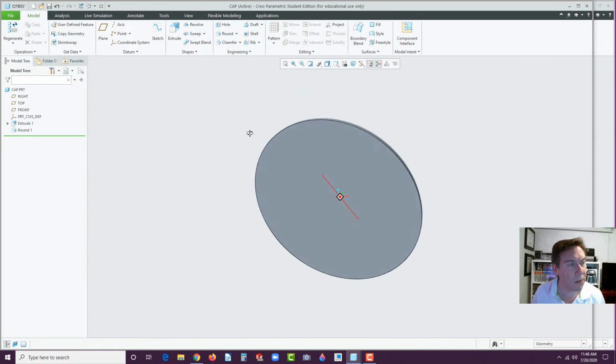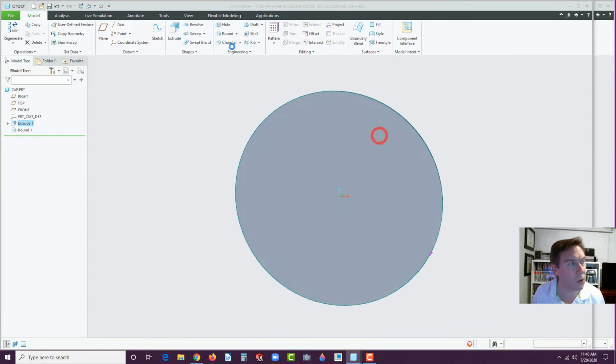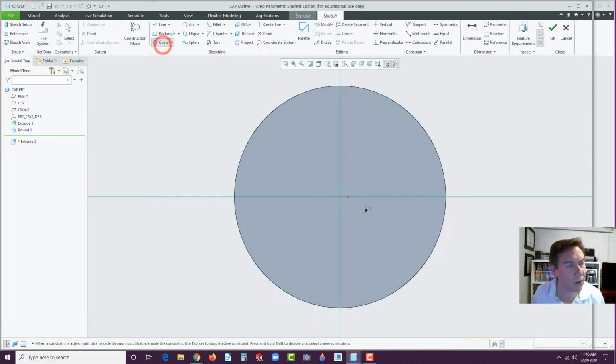Okay, now flip to the underside, select this face, go to extrude, go to the circle tool, and right at the center, drag out a circle and dimension this 1.8, so it steps just a little bit smaller. Remember, the top was 1.9. Now go to OK. Now, here's where my best and brightest students make a mistake. Catastrophic error of drawing the circle on the inside of 1.5. They're not the same depth, so don't try and put them together. This extrusion here is going to be 1/2 inch. The hole is only 0.4 deep, so it's not even a full 1/2 inch.